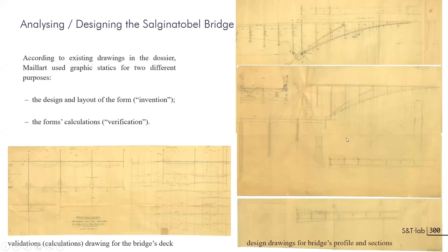And you see that according to this line, and considering the transversal section with its own inertia that will influence the level of the center of gravity, considering all these aspects, he will be drawing again and again the lines of the lower chord of this bridge. So he uses graphic statics in an interactive approach to design the geometry of the forces. Of course, there are other drawings just for analysis, but I will be focusing here on graphic statics for design.